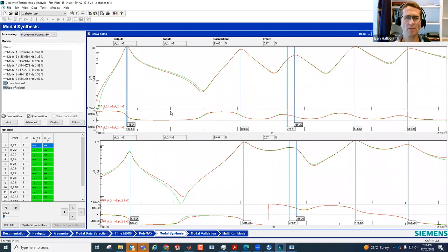The purpose of this particular workbook is to allow us to compare and contrast the mathematically fitted data to our experimental results that are being used to animate the shapes that we're reporting when we do an experimental modal analysis. And this is a very important part of the process. It's no good just producing mode shapes and hoping that they are valid and then reporting them without understanding what's happening to produce those results. And so these are the mathematical models that have been fit as part of our picking of poles within the stability diagram, and this is the result.